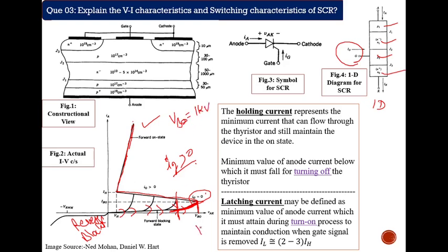This 1 kilovolt rating you can achieve if you are decreasing the breakover voltage using the gate current, then the 1 kilovolt rating is still there. So you can use your device in a safe zone, and then again increasing the gate current, you can fastly turn on your thyristor.